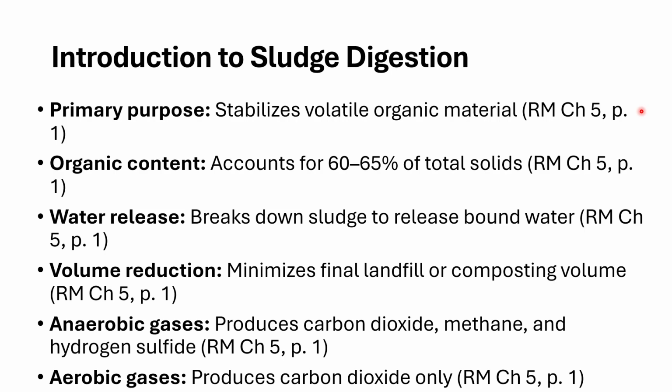Okay. In addition, when we look at the secondary clarifier, that secondary sludge, some of that waste activated sludge, we're going to recirculate like 2% of it, but the majority of it's going to go to waste, which is the digester. Okay. So the idea with the digester, we talked about last go round, talked about solids handling. The digesters are a biological method to thicken our sludge. What we're basically doing is using these microbes, these bajillion microbes, if you will. That's the scientific term, bajillion microbes. And those microbes are digesting the sludge.